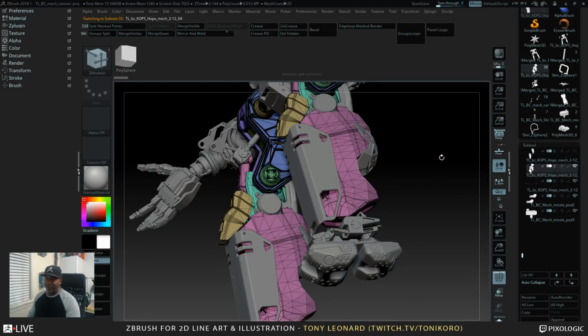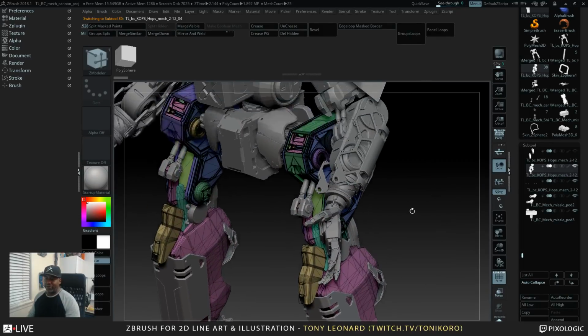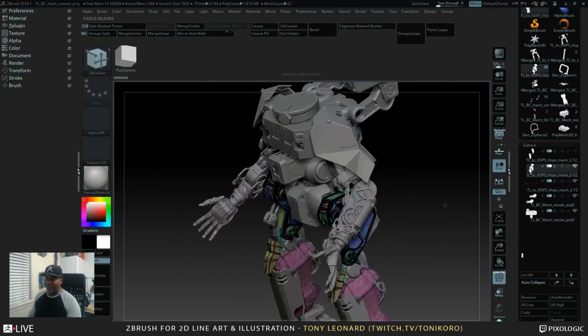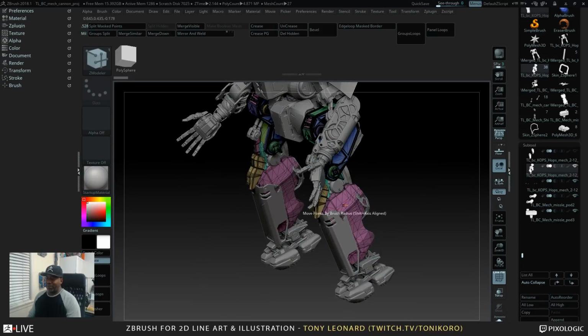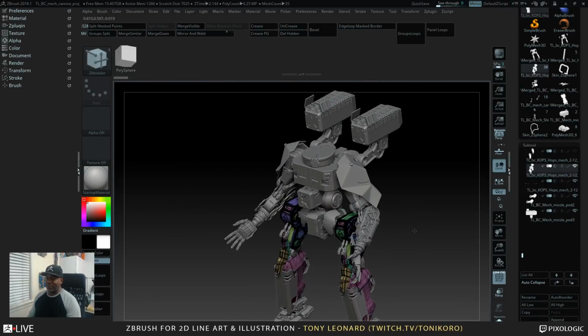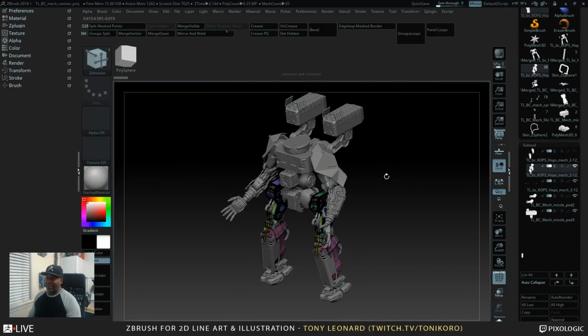But yeah, when I'm working from Blender, I bring it back to ZBrush, a lot of the shapes are triangulated, but I do retain the polygroups. And so when you save or export out from Blender, make sure you have triangulate and probably polygroups turned on, and it should come back into ZBrush in a manner that's not only pretty clean looking, but you can still grab the parts and separate them out if you need be. You could dynamesh a lot of these and start sculpting and cleaning up the forms. So as a conceptual way of working, that's really cool.